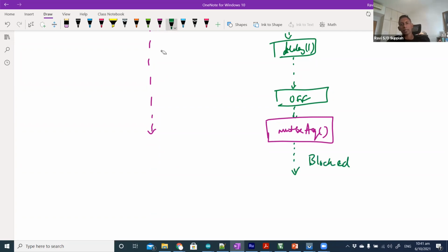It does not matter that the green task was the one that actually acquired it earlier. All the OS looks at is, when the task tries to do a mutex acquire, it will observe the current status of the mutex. If it is available, it will allocate. Currently it is considered not available because a task already acquired it. So the same task acquiring it again is still considered a second acquire, and it will go back into a block state.